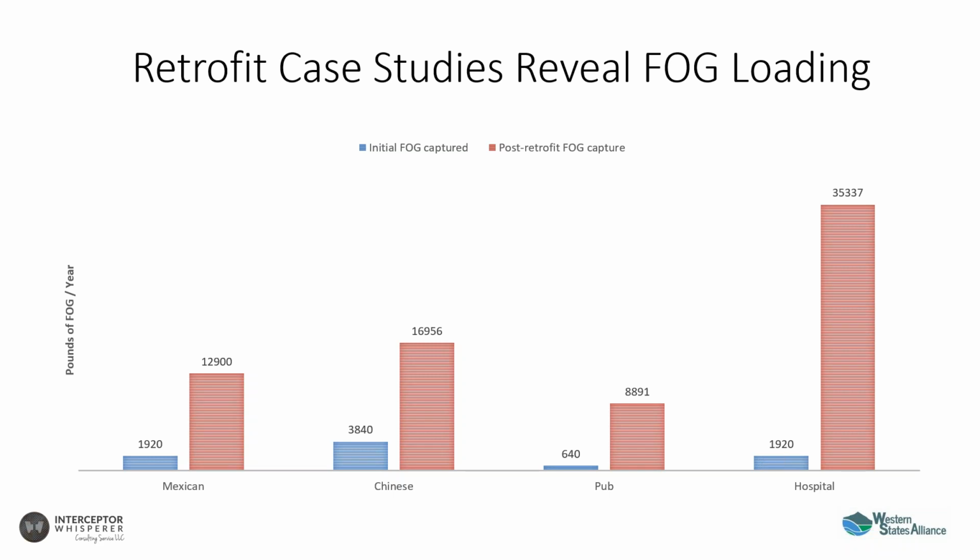But this is a pretty good illustration of the difference between having a restaurant that's designed under an old code. Here in Oregon since 2013, any food service establishment has to hook all fixtures and drains in the kitchen and food service area up to an interceptor. The only exception is the bathrooms, the sanitary drains, and there are a couple of other exceptions for condensate drains. But if there's a floor sink or a floor drain in the food service area and an ice machine goes into it, that drain will be connected to the interceptor.